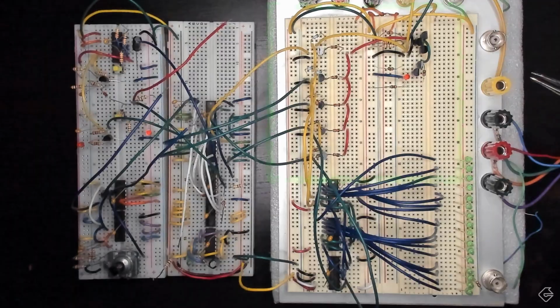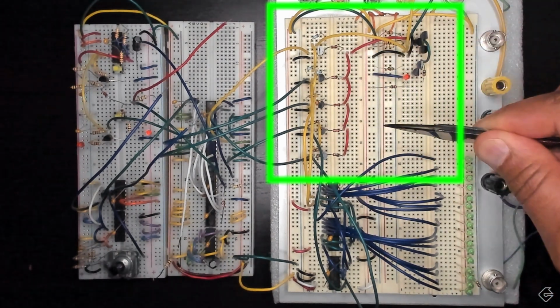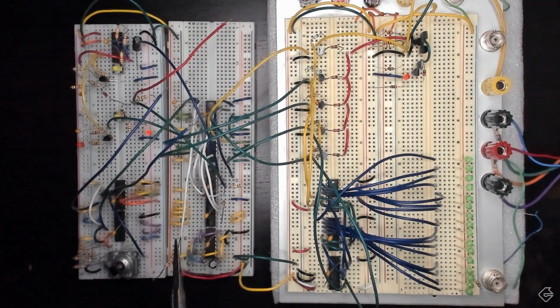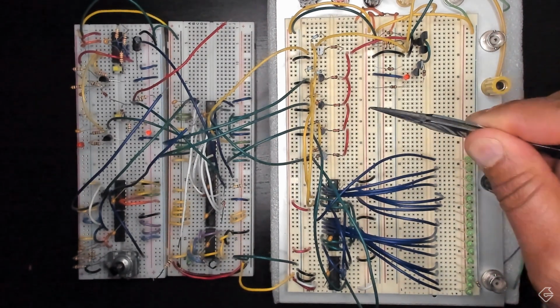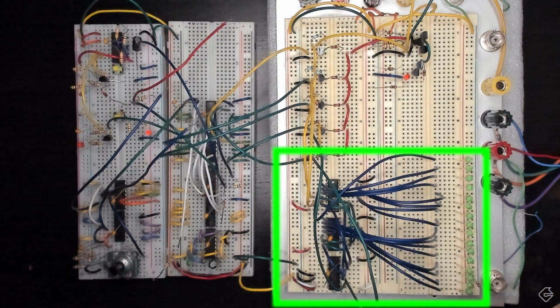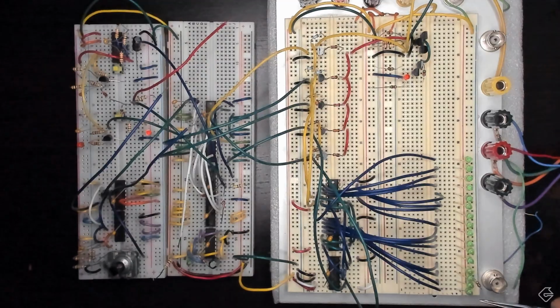And on the right side, on the top over here, we have the actual driver circuit, which takes the signals generated from this logic center and drives the actual LEDs according to a proper intensity level, basically controlling the current. And down here, we have another optional component that will give us an intensity indicator. So when our LEDs are low intensity, the light down here will illuminate. And as we increase the intensity, it goes all the way to the maximum up there. Those are a lot of components. And like I said, we can cram them all into one board, but I think we can do better.